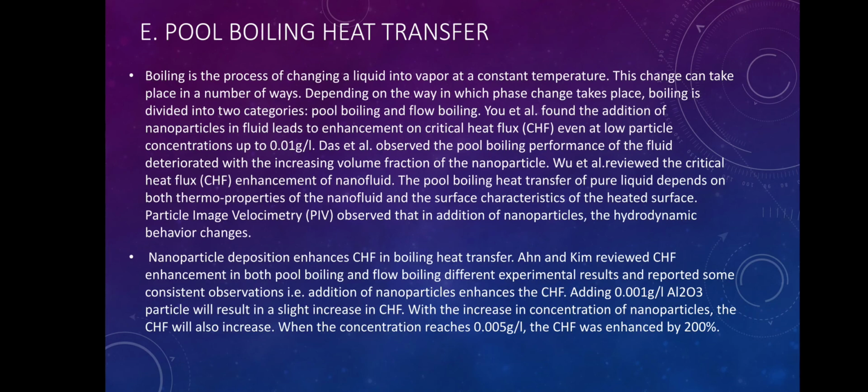An and Kim reviewed CHF enhancement in both pool boiling and flow boiling from different experimental results and reported some consistent observations, that is, addition of nanoparticles enhances the CHF. In addition, adding 0.001 gram per liter of Al2O3 particles results in a slight increase in CHF, with an increase in concentration of nanoparticles. The CHF will also increase when the concentration reaches 0.005 gram per liter. The CHF was enhanced by 200%.